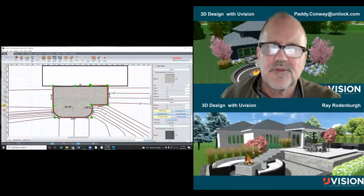But if I go to shape options, copy shape, go to landscape, or terrain, sorry, area grader, that famous button of mine, shape options, paste shape, you can see what's going to happen now because it jumps up automatically to the 6 feet that we've seen throughout the course here. And I'm going to bring this height taper up, but let's bring it down to grade first. I'm dropping this whole patio to an area grader that is going to match.